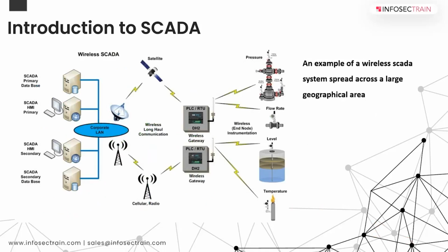This is another configuration of SCADA. Probably this is offshore here. This is another offshore facility where you have different instruments or equipment, and an RTU with the PLC inbuilt in a wireless gateway. They communicate through radio and satellite, and they are linked with the LAN to see all the live data.